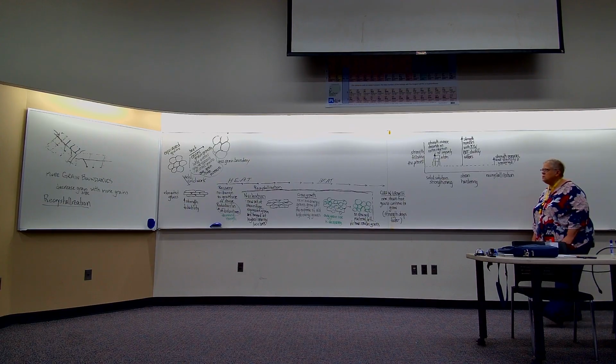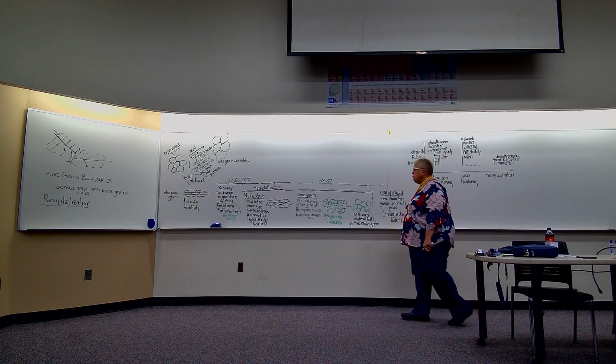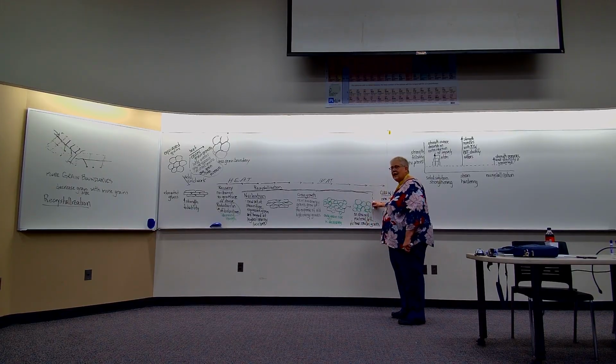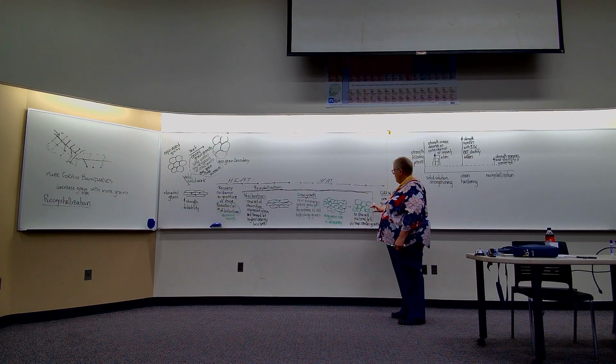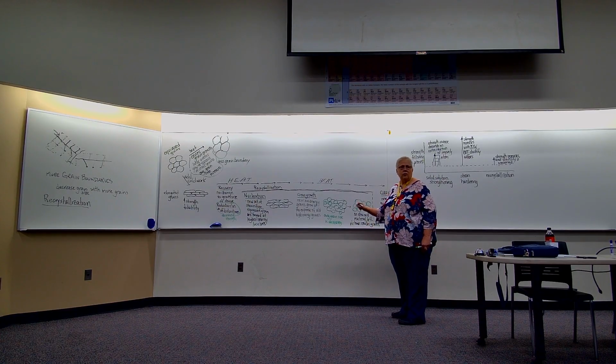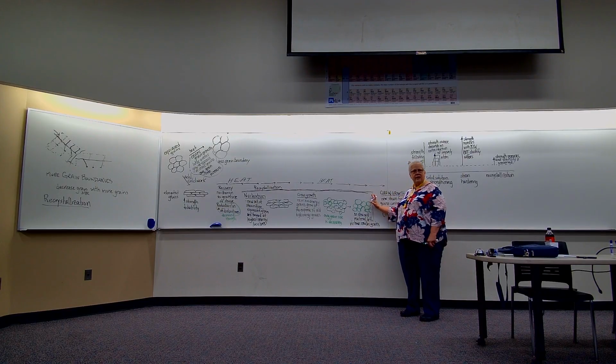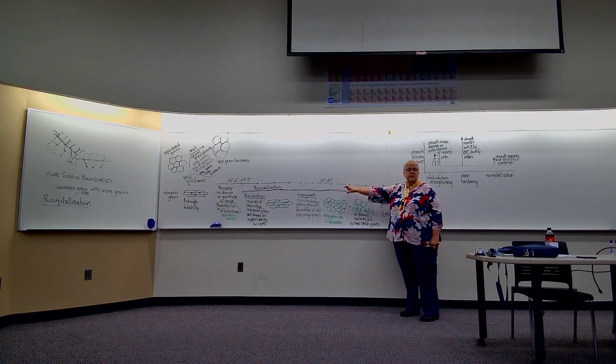Now, the time at which this happens is dependent on what you start with, how much cold work you add, what material it is. How long this recrystallization process takes isn't standardized. If you use this application, you'd have to figure this out. You'd have to do some experiments for your material to determine what time is this, how many hours, how many seconds, how many minutes. Of course, that depends on the temperature you're using.